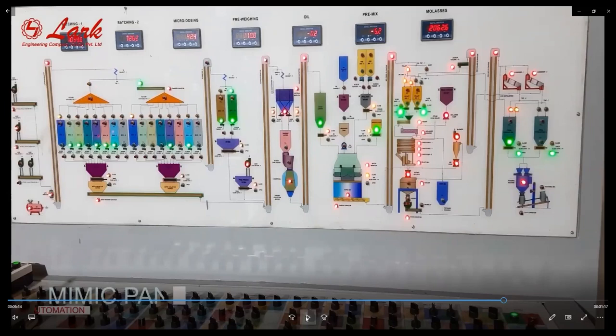And the second new thing we introduced is the optimum life of parts. If we run the hammer beaters beyond their specified life, the corners of the hammer mill beater become round after some time, and due to the round corners the texture of the feed changes. With the changed texture and coarseness, there is more recycling, less conditioning, less steam and moisture absorption, and poor PDI. We may have saved 10 rupees by running the hammer beater a little longer, but we lost heavily in recycling, power consumption and feed quality.